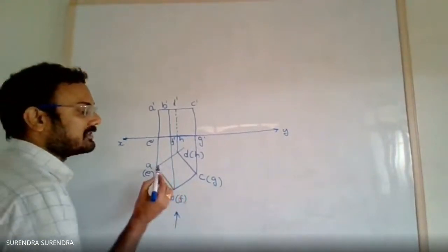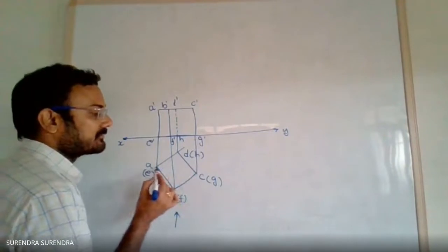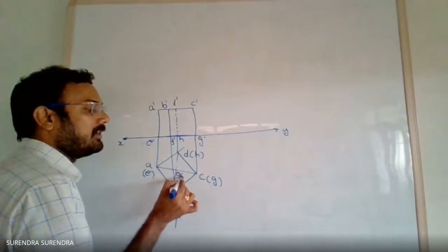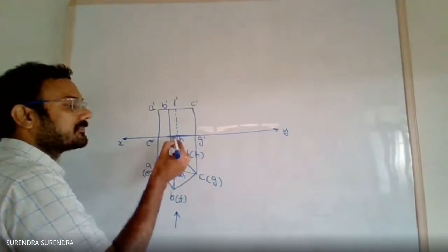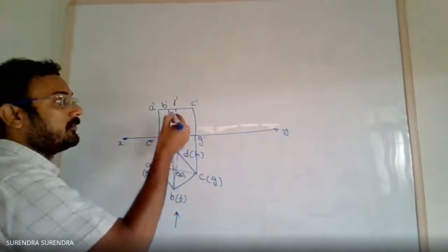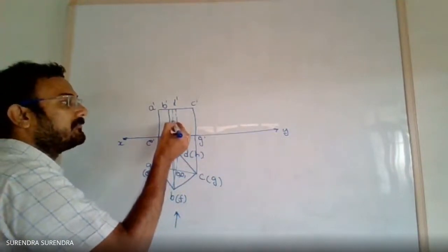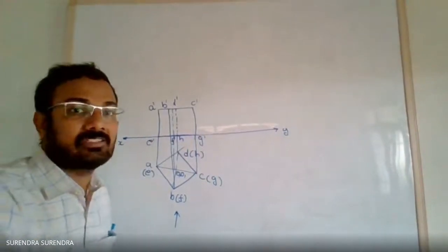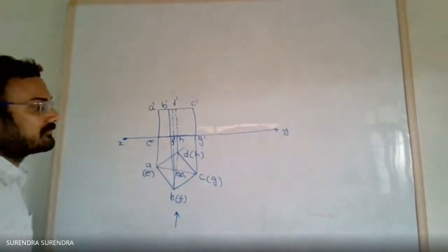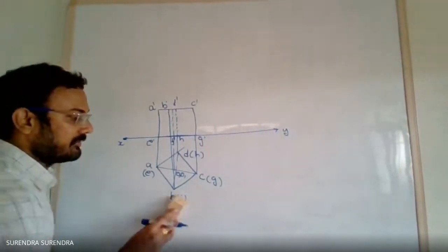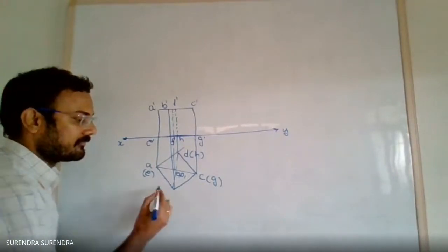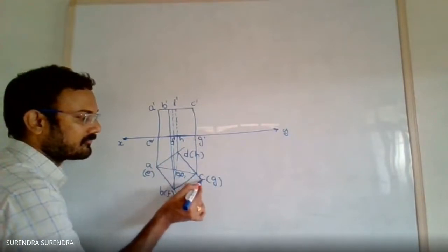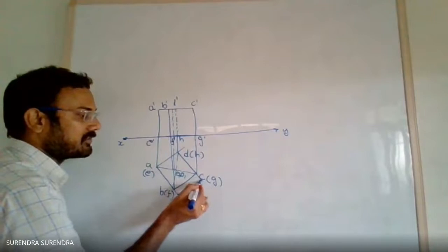For drawing the axis, join the diagonals with a 2H pencil to get the intersection point. Mark this as O comma O1. Draw the projection from O comma O1 and indicate the axis line. Finally, the dimension. Represent the dimension on any one side: side length equal to 60 mm.